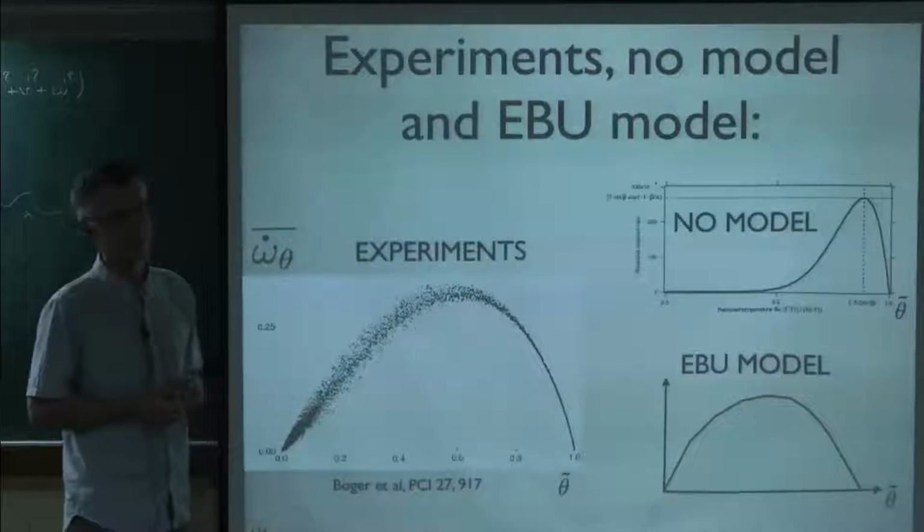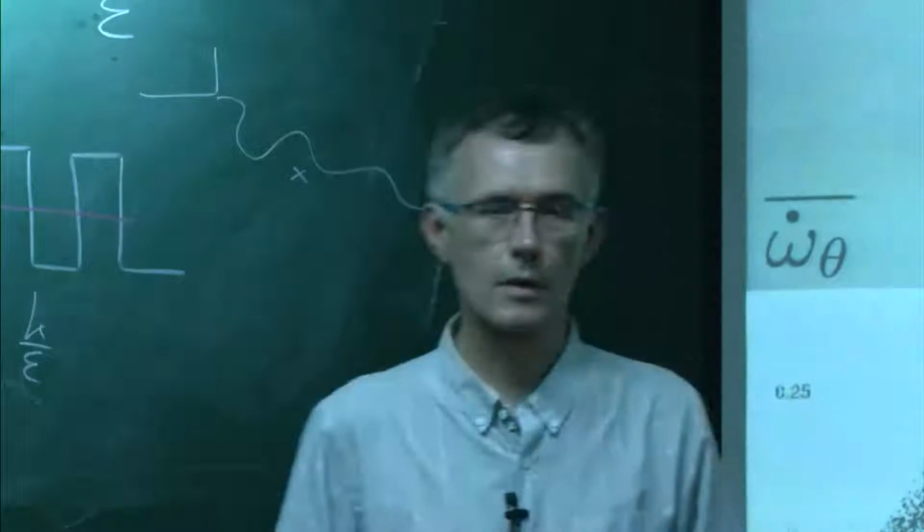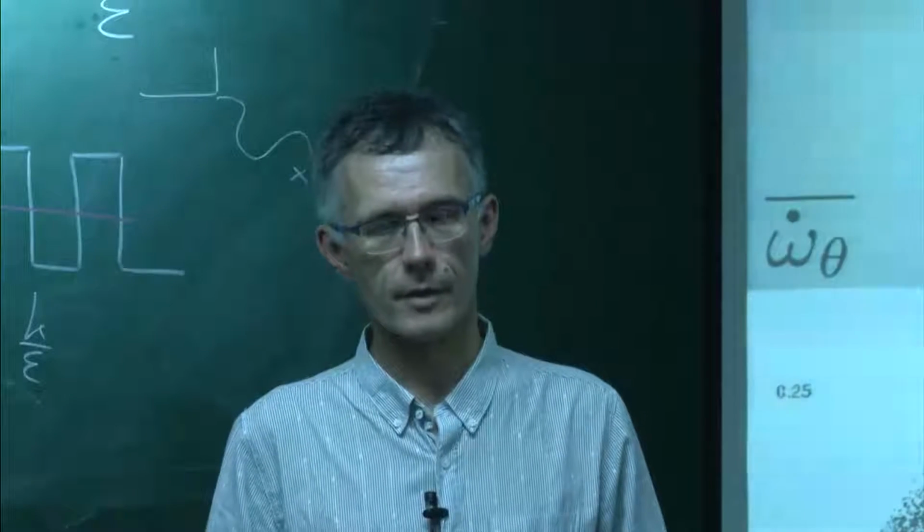That's the point. Sir, in the Fluent simulation, if you use the EDM model, the eddy dissipation model, we don't need any patching of a high temperature source to ignite the flame.